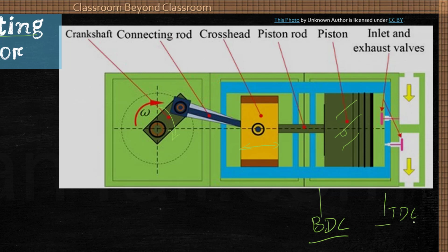Since the temperature increases because of the compression, there may be a cooling jacket. It may not always be present, but in this diagram the blue parts are the cooling jacket, which carries away the heat produced during the compression. Now just see, this is the inlet valve.